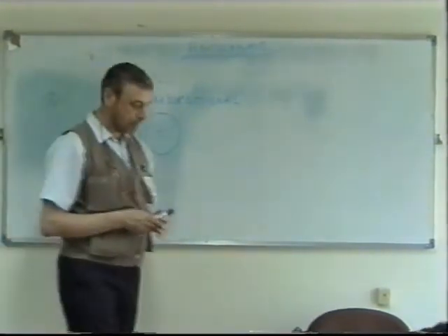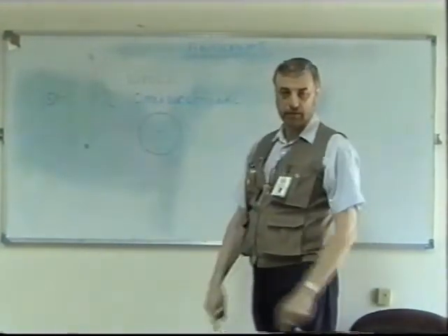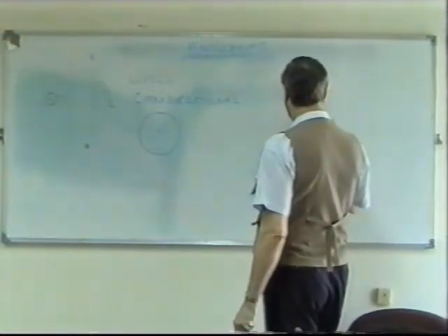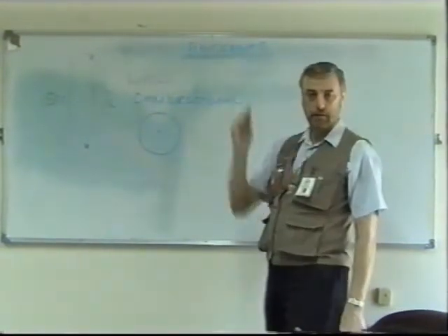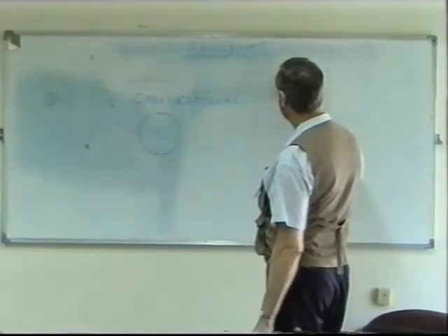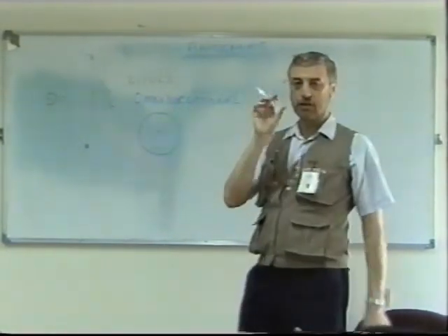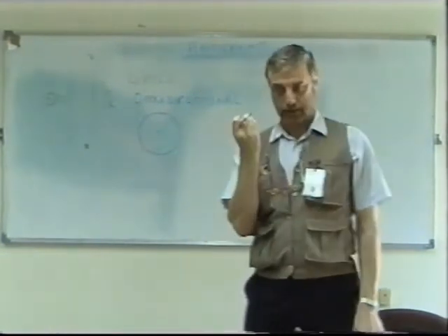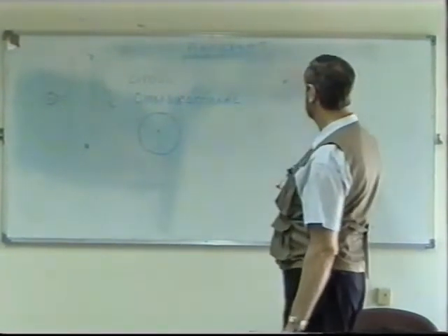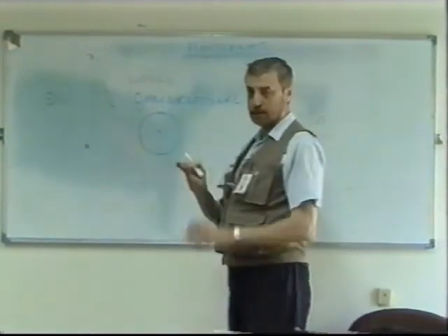Basically, if you imagine how they would make a polar diagram in practice, imagine they have a large area, like a large field, several acres, and they have a building in the middle of the field with the antenna on top of the roof of the building. Now, if this was a dipole antenna, they would then get into a truck or a car which would travel an even distance around there with an instrument that measures the signal strength, how strong the signal is, as it moves around. Can you imagine that? Same distance away at all times, but moving around here. And then it plots this on a graph.